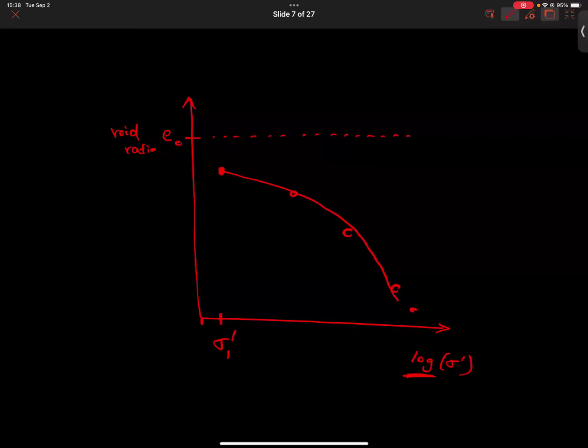In homework and exams, when I give you the void ratio, I always see somebody still plot that initial void ratio point. That is not the case. It's used as a top ceiling. In the experiment, you would show it as a dashed line just to show that all of our data is below that, which should make sense.